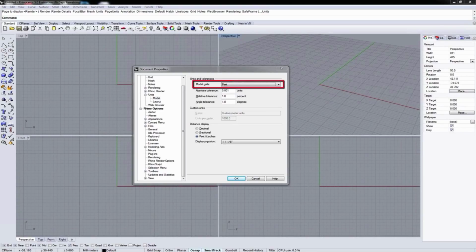One of the things to note is make sure you set it to the ACIS solids in your modify settings. You don't want to export it as polymesh. I'll explain why. Everything in that view is now ready to get exported.